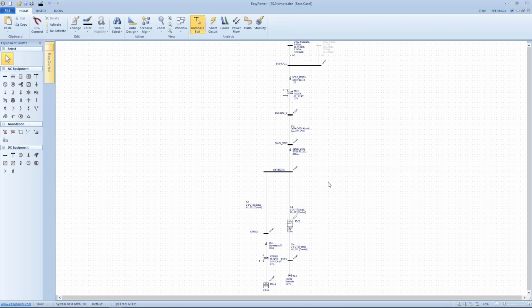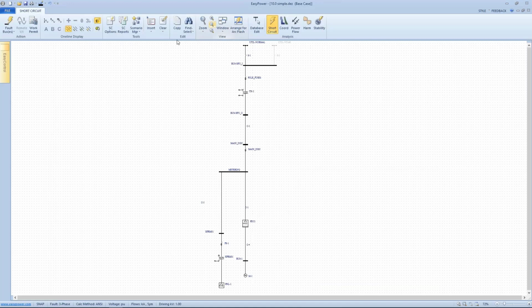And if you look at this, what you're primarily looking for is to make sure that as we've filled in the data, we can go to the short circuit focus and fault all the buses and get labels, or at least the data required for labels, at the locations that we expect and need labels as the ultimate solution.